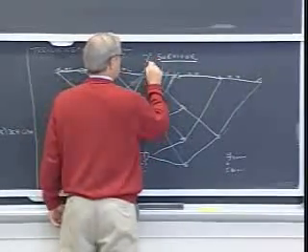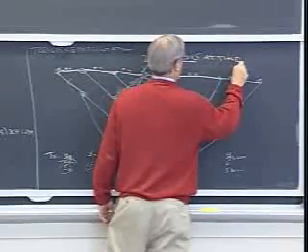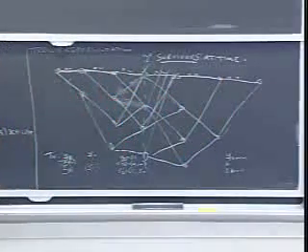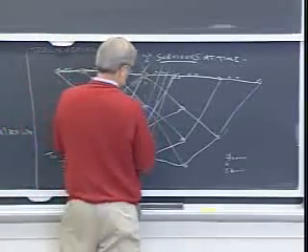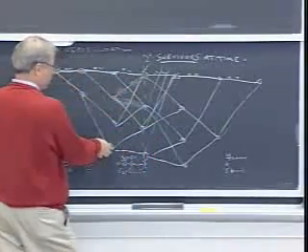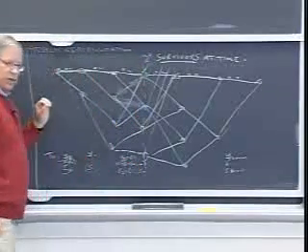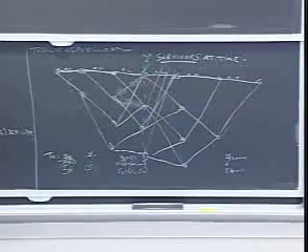So we have 2 to the nu survivors at time k, or time i, whatever your time index is. I used k for something else. Okay, so I can throw away half the possibilities. Now, for each survivor, I remember what its past history is, and I remember what its cost is to that point.